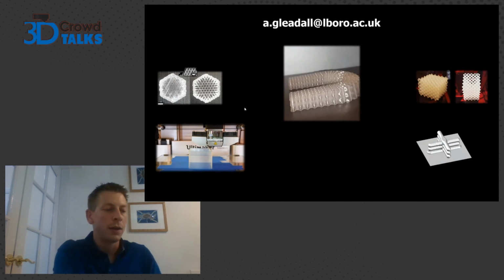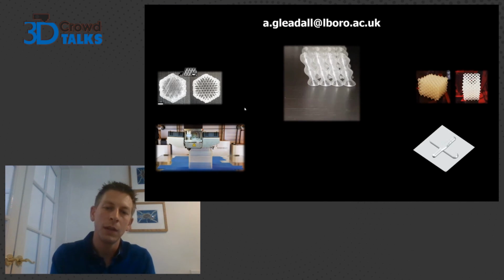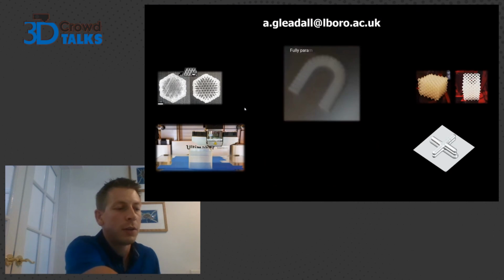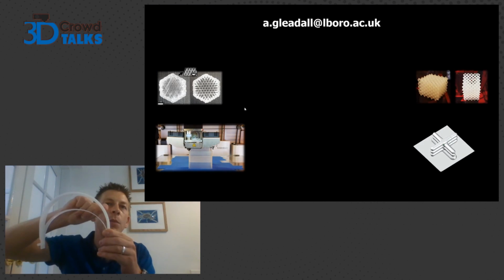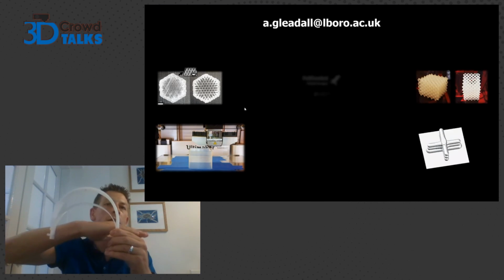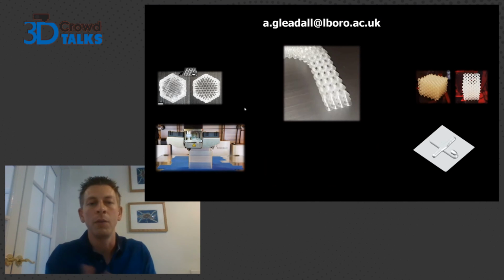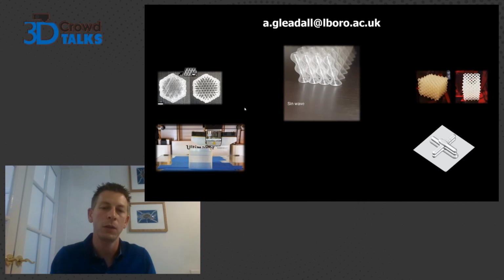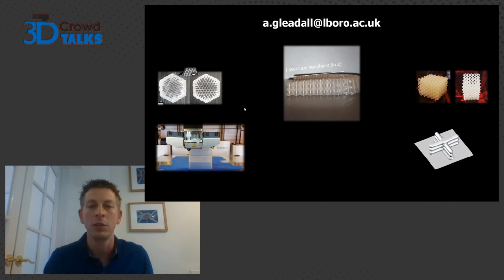The whole design of your structure has got to be at the scale of those individual filaments, so you have to know exactly where you want them to be. For this arc, which might be made up of, say, 360 filaments, each little segment, you don't need to define that, but you do need to define the center point of the arc, the fact that you want it to go from this angle all the way to that angle, and that kind of detail. That's why it's full control: to take that simple information and produce all the tiny little XY coordinates for the G-code. But yes, it has to be thinking at the actual individual filaments' position, size and location.